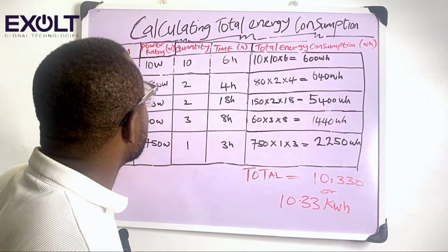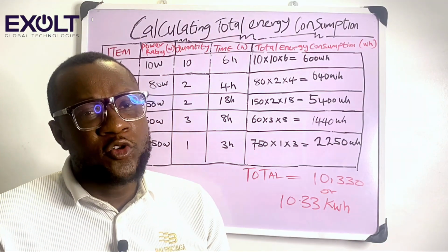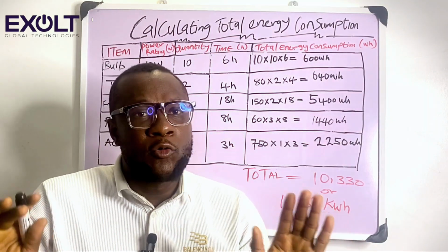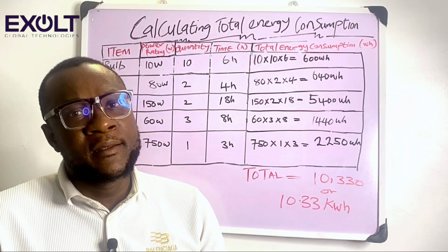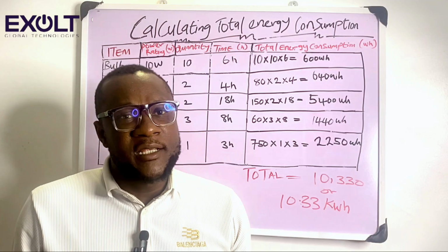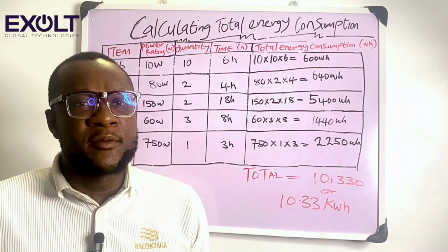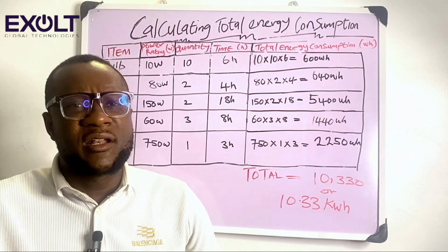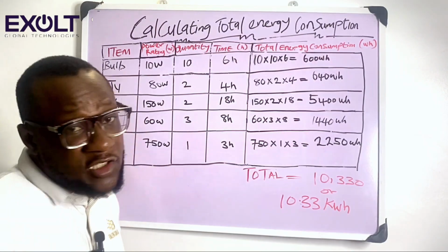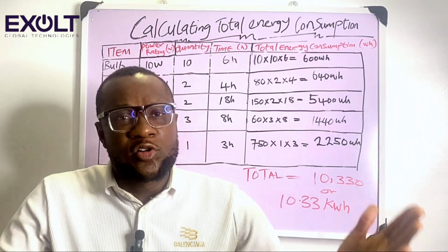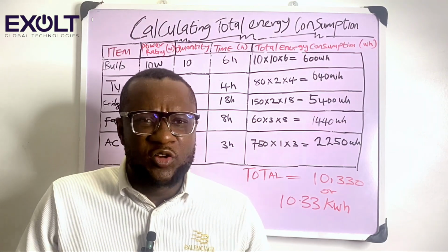In this energy analysis, here are a few things you must consider before you can properly understand the nature of the job you must do. As a professional installer, you don't just design your solar system based on the size of the house, or the location of the house, or other parameters, without understanding the total energy consumption. It is the gadgets in the house that consume the energy, not just the size, structure or location of the house.